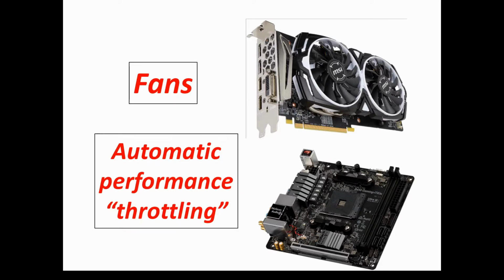Now, the other thing is you've got to understand what is really bad and what isn't that bad, because I think people tend to think that more heat is bad and stuff is going to melt. And that's not really true. There is a lot of stuff that engineers design in to make sure that it doesn't melt. Just because it's getting hot doesn't mean that's bad, okay? There could be things that maintain it. Usually engineers design your equipment so that it maintains a temperature below the damaging temperature. So if it's getting really hot and the fans are going really fast, that could be a good thing. That could mean that it's doing what it's supposed to, and you don't have to worry about it.